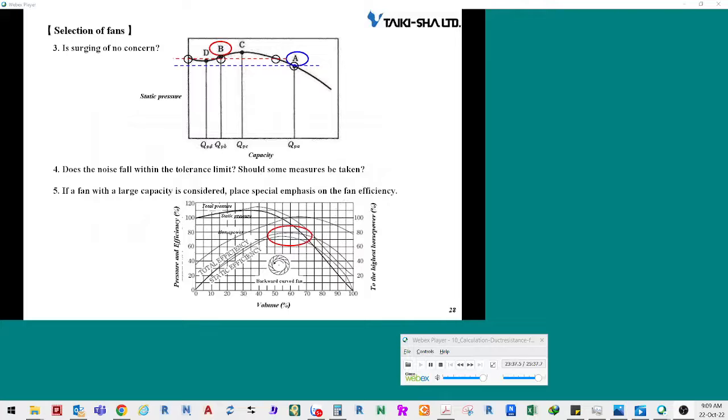In the case of other equipment such as smoke dischargers, different duct routes receive different resistance. Duct routes with high resistance can act as surging zones. Be careful when you establish a duct plan, calculate duct resistance, and select fans. In principle, Take a Shot does not select Sirocco fans for smoke dischargers. Select other fans such as limit load fans for smoke dischargers.